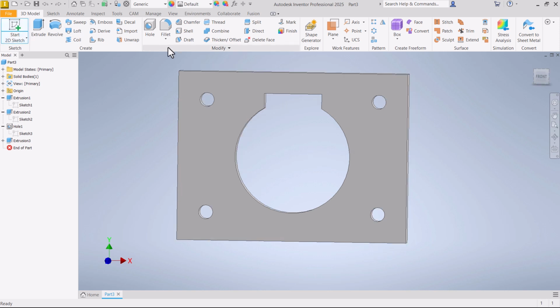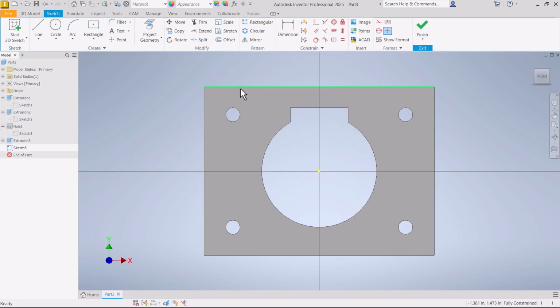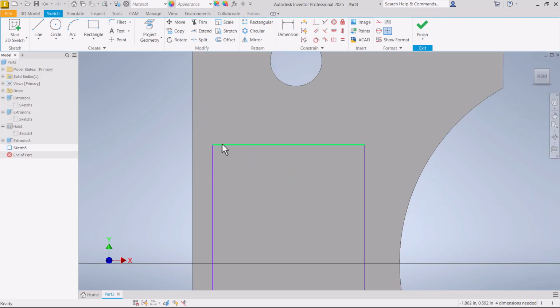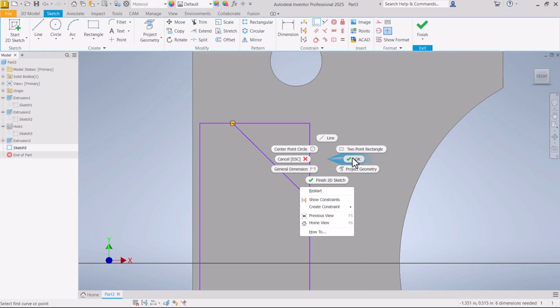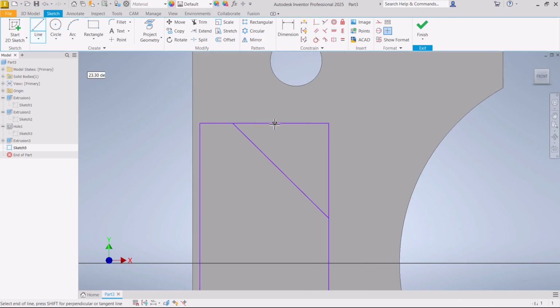So as you can see, the coincident constraint is a very powerful little tool. Everything you do, everything you sketch is going to have the coincident constraint in it somewhere. Even just drawing a simple little rectangle is going to be full of coincident constraints. So practice using this constraint. Practice deleting the constraint. Click on the line, see the constraints that are on it, so you can delete them, so you can go back and reapply them. See all the different ways that you can use a coincident constraint, whether you're applying it directly or it is being applied for you as you draw.